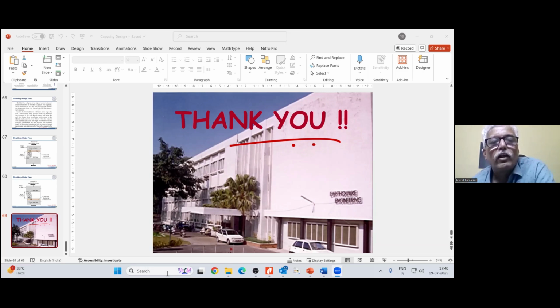One is what will the cover be if boundary elements are provided? As per the sketch shown, clear cover may not be maintained. Please confirm, because as per the minimum columns, cover is to be maintained. Whatever is required from the durability, that is to be maintained from the outermost rebar.